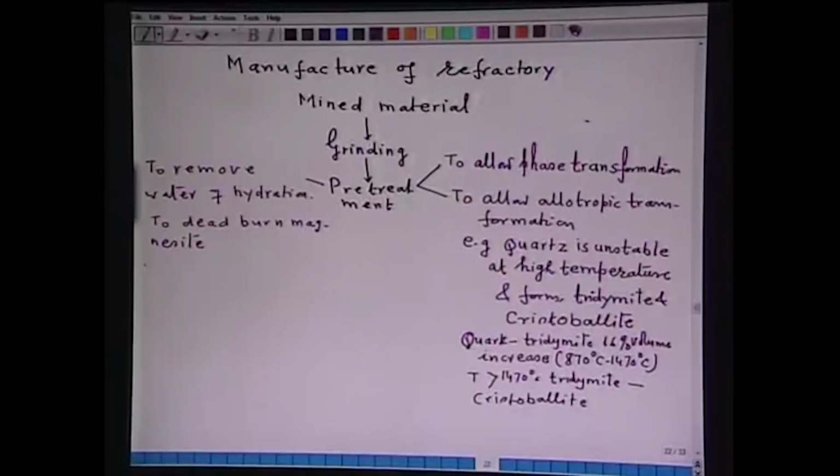Another important thing, in fire clay, mullite formation is important, because the mullite imparts resistance to slag as well as high temperature strength to the refractory material.